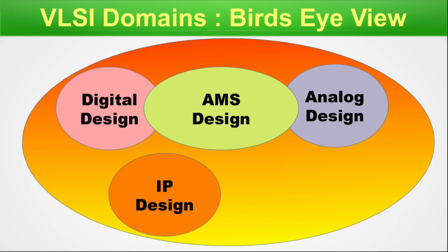For this, there exist two more very important domains. The first one is IP design. Here we make unit cells or design blocks. Standard cell is such a famous set of IP collection which every digital design needs. A set of standard cells will contain combinational logic gates, sequential elements, level shifters, and many other important cells needed for the physical design. Analog IP examples are DC-DC, PLL, A to D and D to A converters, any kind of unit memory cell, etc.